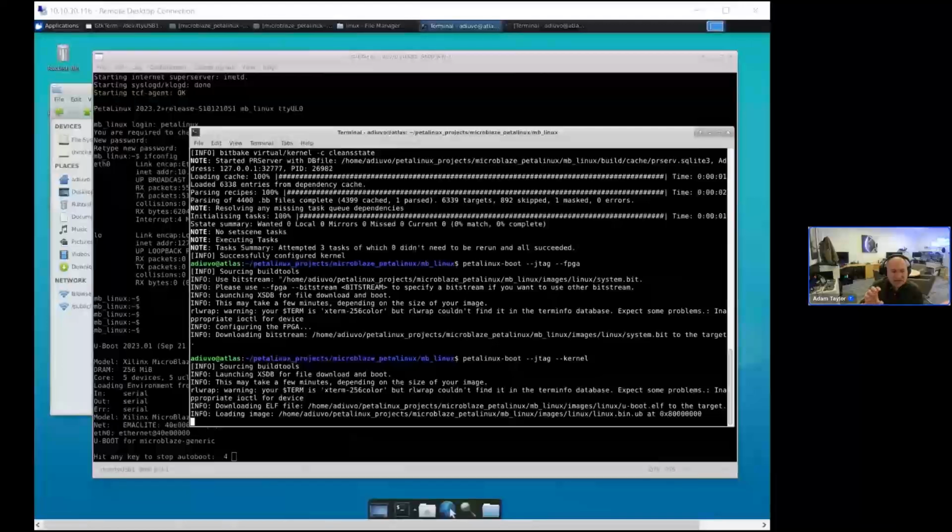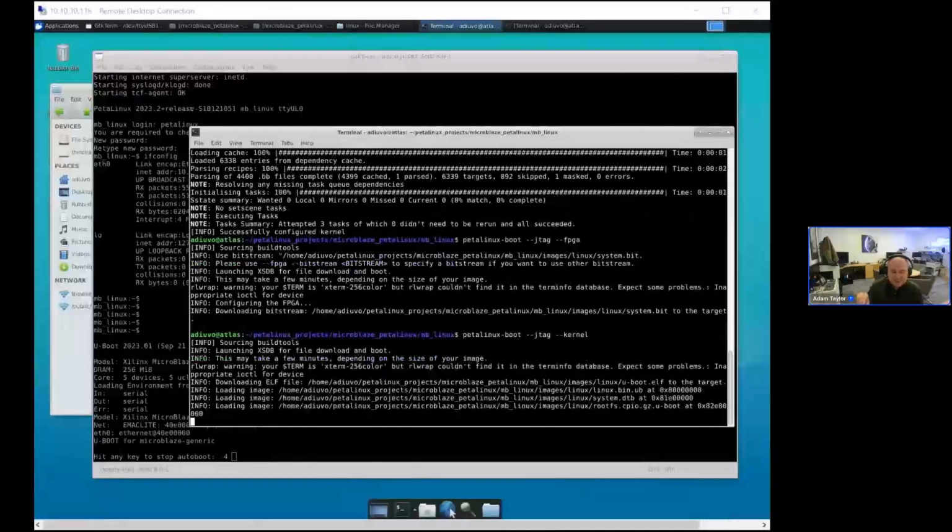But you can actually use a thing called UIO and write a simple device tree update actually to tell it what to do. And then you can access it and treat it as though it's your own peripheral and just read and write it using the Linux UIO elements. Honestly, this used to daunt me a little bit, but actually it's not so daunting now.